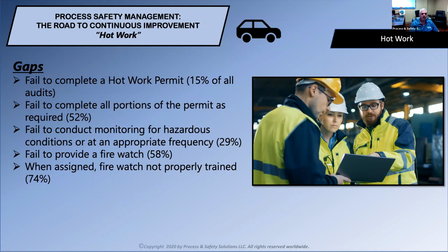The other thing is failure to provide a Firewatch. 58% of the time we see this. And this really goes beyond just having somebody there that's been provided as a Firewatch. When a Firewatch is assigned, it means that that person's only duty is to be a Firewatch. If they are doing actual work, they are not a Firewatch. Even though you may designate that person as a Firewatch, if they're involved in the actual hot work itself, then they're not a Firewatch. A Firewatch is dedicated; that's all they do.